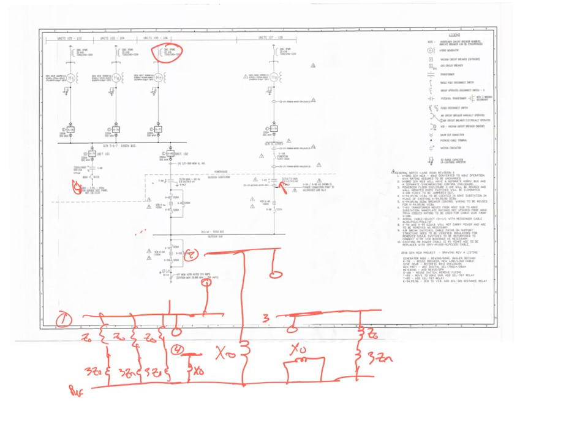Remember we talked about a high resistance grounded system, low resistance grounded system, and zero impedance grounded system, or solidly grounded system? Are those solidly grounded? Yeah. They are? Or no. They look like they're grounded through transformers, so these are high impedance grounds, and it is important to include that because that's going to limit the ground fault current, isn't it? If I had zero sequence current flowing through here, that's going to be a lot lower if this is included than if it's not included.